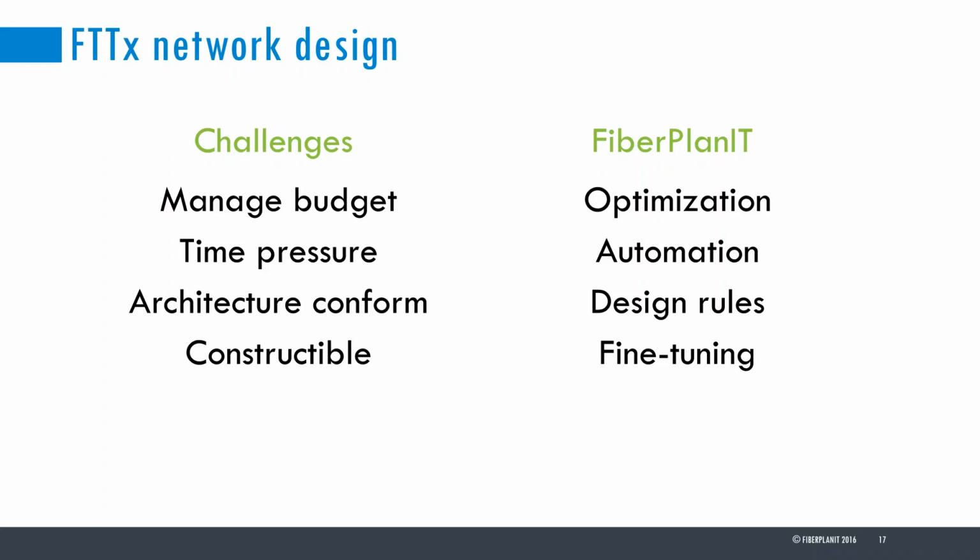We zoomed into the design rules that you can specify, so that way you can make sure that your network design is every time conform the specified architecture and rules you need to follow. And then we also had a look at fine-tuning capabilities of the software. So taking into account field survey input, you can make sure that you get a constructible design in the end by fine-tuning your network design.